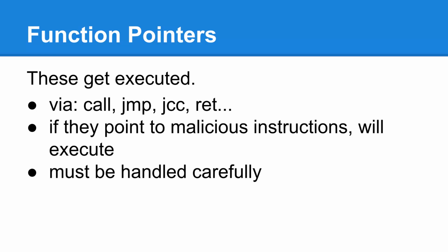Fundamentally, that was originally meant to be a design feature, but now many von Neumann architecture implementations have re-engineered many features to correct that now considered design flaw. Conversely, the Harvard architecture has completely separate physical memory for instructions and a separate physical memory for data. And the EIP, essentially the instruction pointer, cannot ever point to the data part of memory. It is not allowed in the architecture.